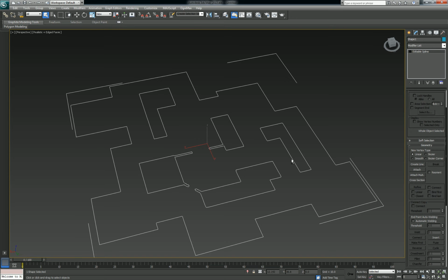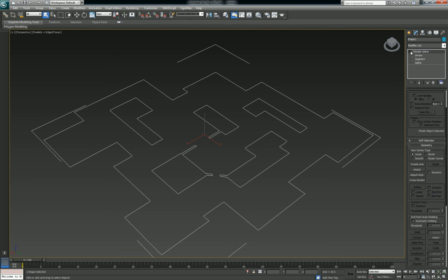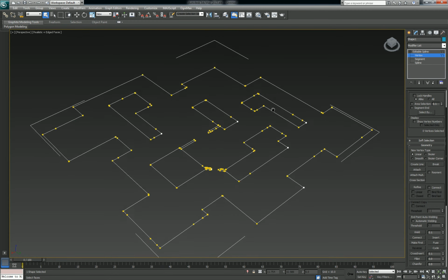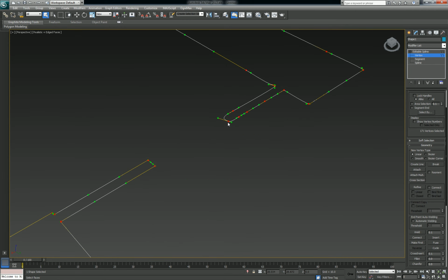As you can see, we now have this brought in, imported as a shape form. Now, a shape form is really just a line. I guess the way to think about it is it's an edge without a face, without any kind of facing that we normally expect for a planar type of object. So this is just the edges of what defines the outer shape. So let's go ahead and select vertex selection, and if we select them all, you can see they come in automatically with curved tangent handles.